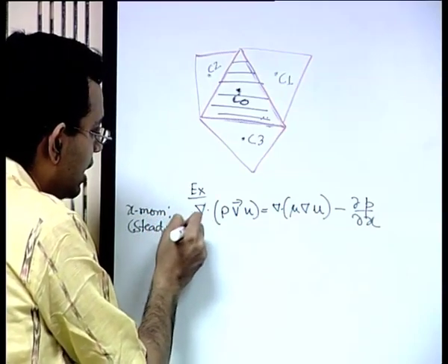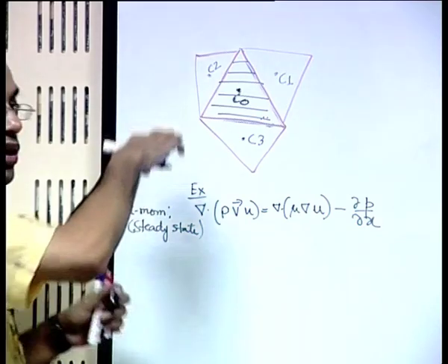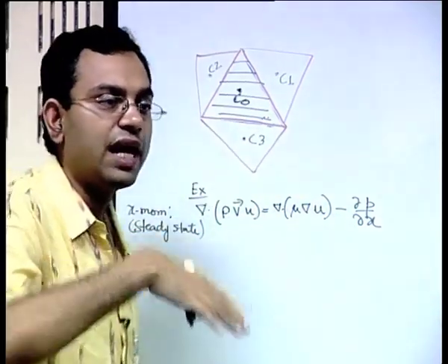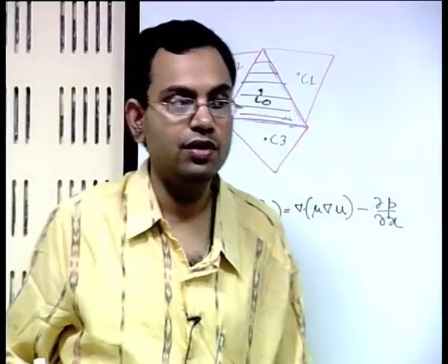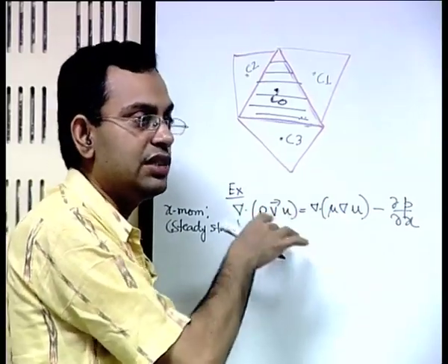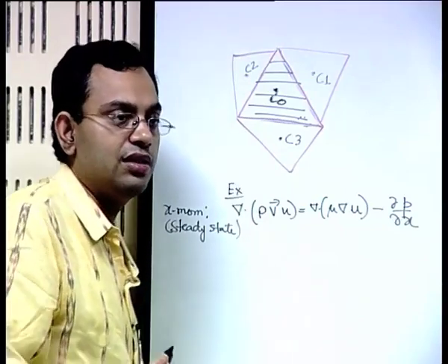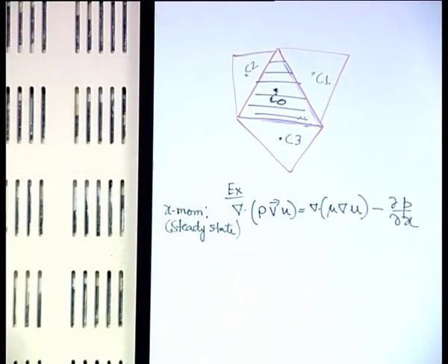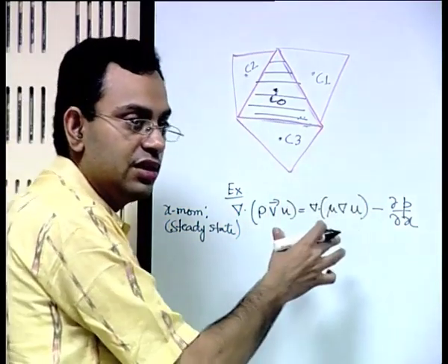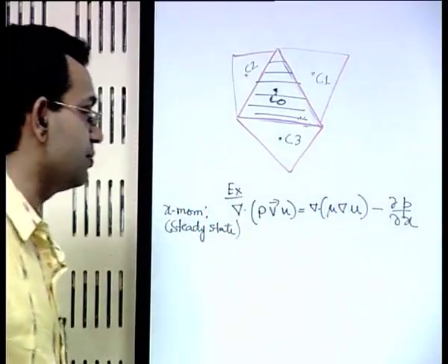The unsteadiness, how is it discretized? It is discretized in the same way. Unsteadiness does not depend on the shape of the control volume, it is a time domain, it is not a spatial domain. So that is why we do not want to unnecessarily complicate it by putting in an unsteady term. If you put an unsteady term, it is discretized in the same way as what we do for structured grid systems. For the spatial discretization, unstructured and structured will differ, and let us see how they differ.